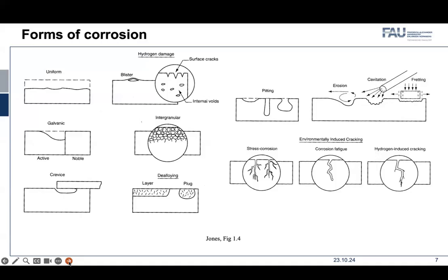And then we have the case where you are welding two metals together. I already described an example of galvanic corrosion happening within the material, where one precipitate acts as cathode and the matrix acts as anode. But a more common example is welding. If you weld some aluminum to copper, for example, it is not happening at the micro scale, but at the macro scale. Or if you weld zinc to steel, zinc is the more active metal. So the active metal gets consumed at the expense of a noble metal.